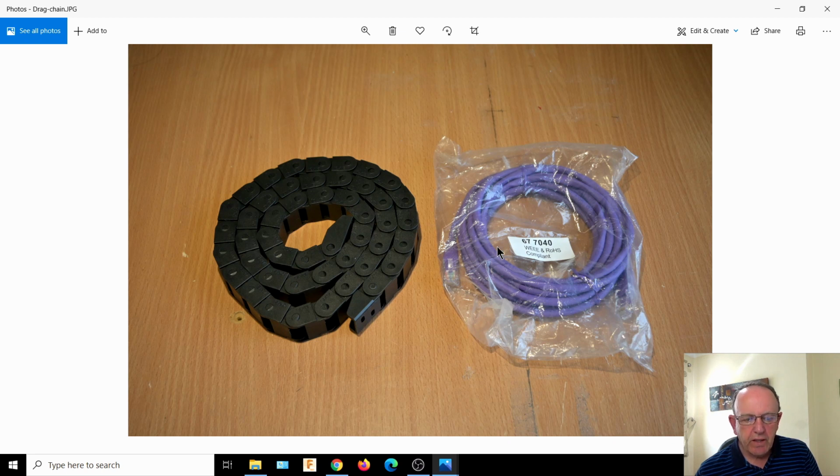Now the gauge of the Ethernet cable is exactly the same as the stepper motors. And because there's 8 wires in here, I'm going to be pairing them up together. Quite a few guys do this on CNC machines. What you'll find generally is that they only take about 70% of the maximum current you've set anyway. So I use this on my own foam cutter, which had more powerful motors, and it worked perfectly. So that's the other update I'm going to be doing.